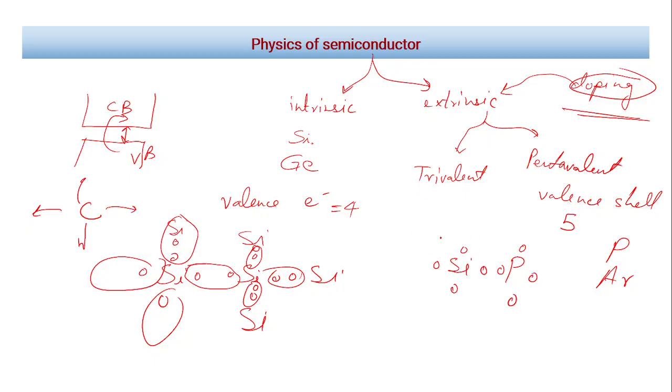It's like millions of silicon atoms with one atom of phosphorus in between. Then there are all these silicon atoms around it, so again they will bond with this. All sides are silicon atoms. So they'll share. But it has 5 valence electrons, so even after sharing, it will have 1 extra electron.